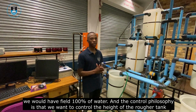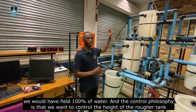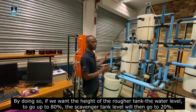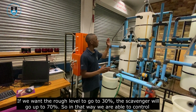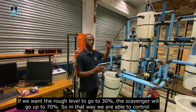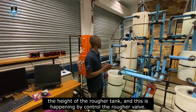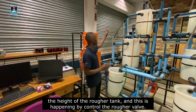And the control philosophy is that we want to control the height of the rougher tank. By doing so, if you want the water level of the rougher tank to go to 80%, the scavenger tank level will go to 20%. If you want the rougher level to go to 30%, the scavenger will go up to 70%. So in that way, we are able to control the height of the rougher tank. And this is happening by controlling the rougher valve.